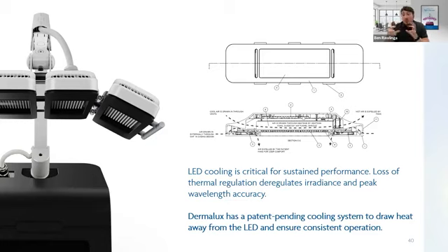And so we spent a lot of time on LED cooling, and it comes from a combination of the actual LED specification itself and how we draw the heat away from the LED into the board, but then also how we pull it away from the board and dissipate that heat. Fundamentally, it's just the most important element of how we ensure the consistency of the device from minute 1 to minute 20 of the treatment, but also throughout the lifespan of the device.